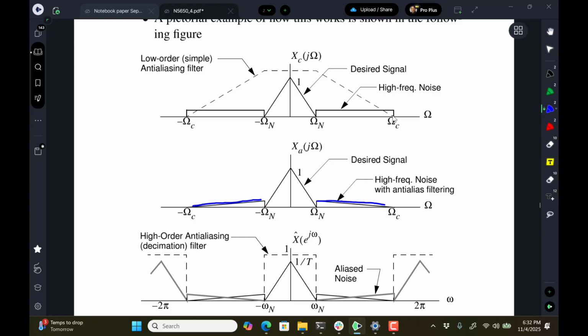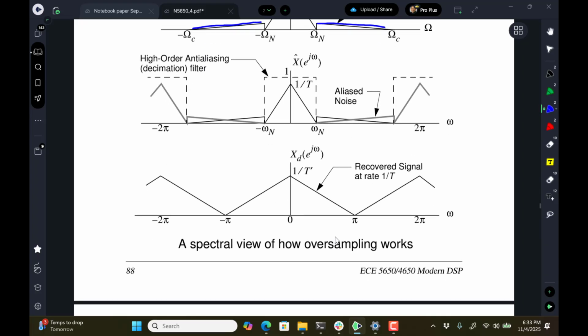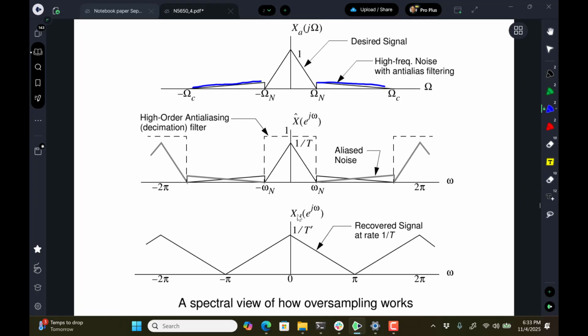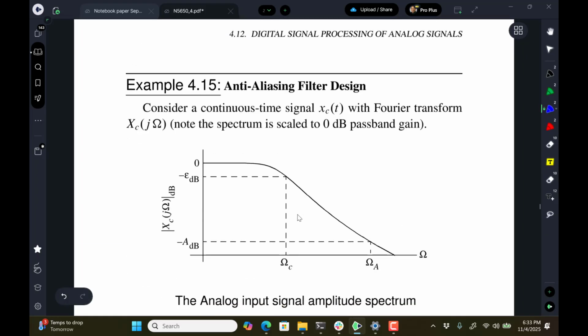So the folding that happens mostly happens up in here, and then we get rid of that, and then we end up with, this is an idealization, but in the third edition of this book, they added in this example, and this was something I'd been talking about before then, but it's kind of a cute example of trying to motivate the idea that oversampling is powerful. I went ahead before this example, and I assumed that the spectrum of interest might have a Butterworth shape to it. It has a cutoff. It has a roll-off rate of so many dB per octave or decade.